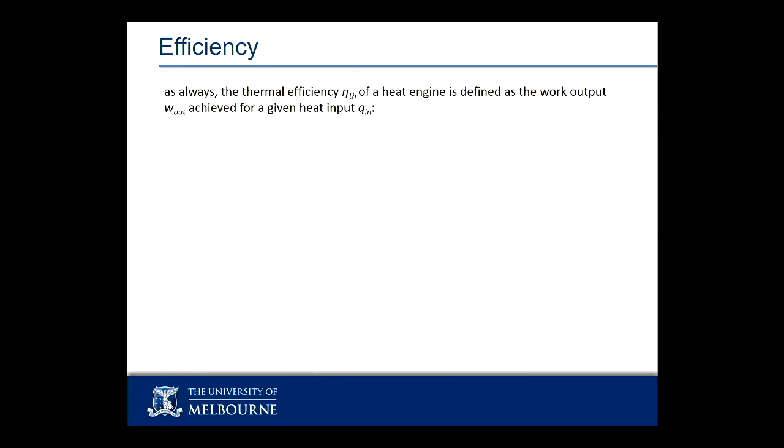And as I said, our main objective will be to write down an expression for the ideal Brayton cycle efficiency. So we have an expression already for the Carnot efficiency, which operates between the flame temperature and the outside world temperature. But now that I put in these constant pressure processes instead of isothermal processes, I will have a different number, which will be the best possible gas turbine efficiency between those temperatures. So let's have a look at how that looks.